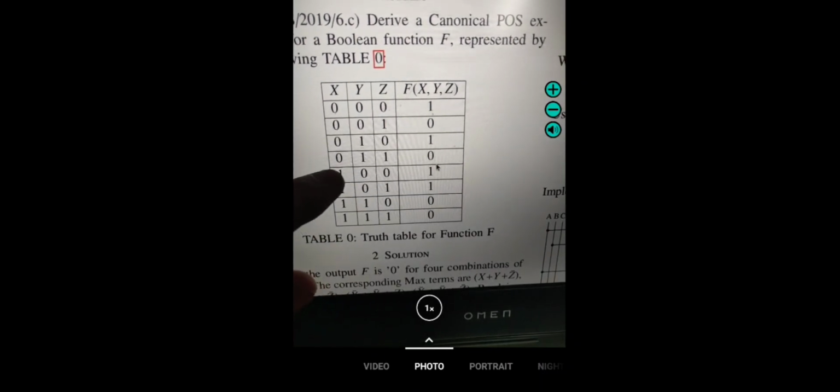So I will keep this 0 case wherein A and B are 0 and C is 1. We should get 0 output. Both the LEDs should be off. And then a 1 case I will take wherein A is 1, other two are 0, and we will get 1 output. So these two cases I will check. I have taken these two cases randomly. We can check for other cases as well.